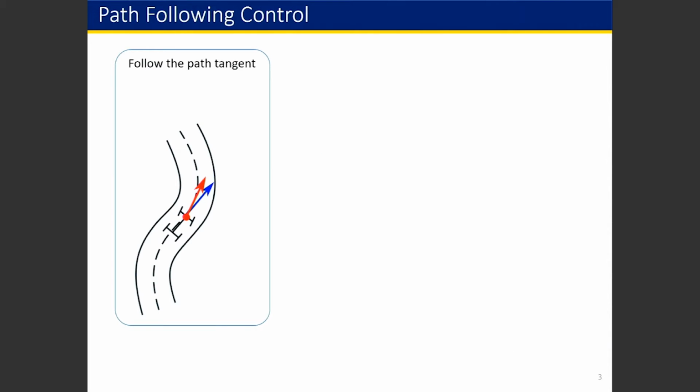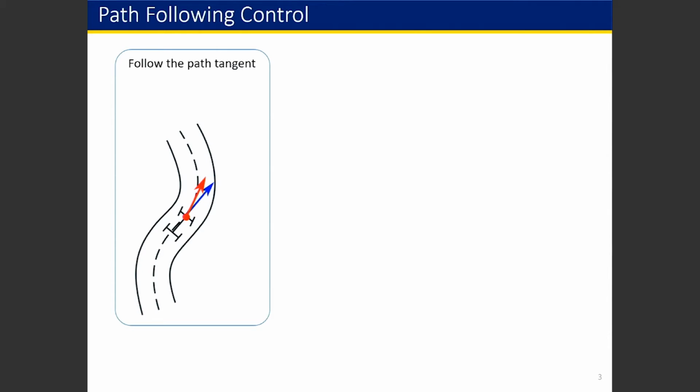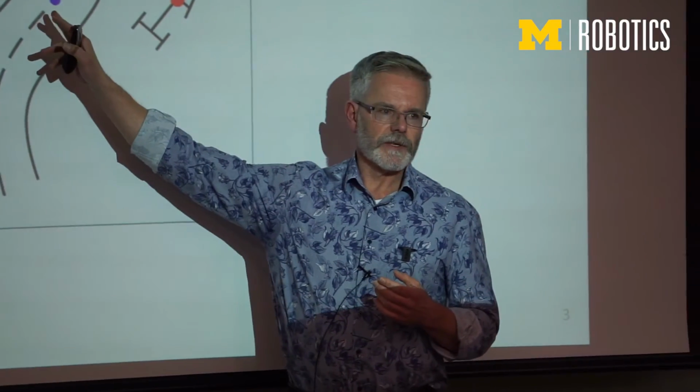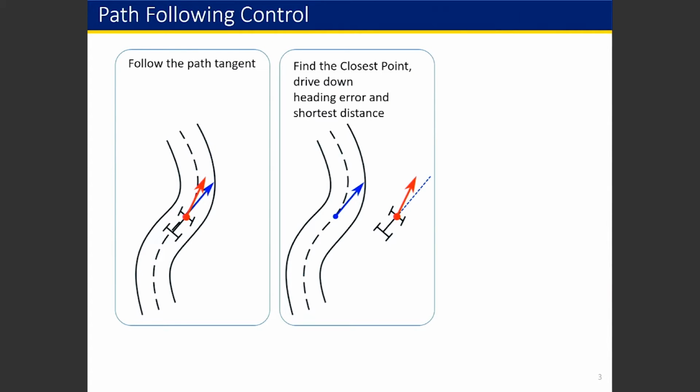It's all about following a path, simple geometry, and in 2D in the plane, we know this problem quite well. Producing path-following behavior from a vehicle, here the kinematic car, could be the bicycle model, is a relatively straightforward task. If you're on the road, in particular if you're in the middle of the road, just follow the path tangent. But if you're off the road, you've got to do something a little bit more sophisticated. There'll be a steering angle that you need to control. If all you do is follow the path tangent, say of the closest point to where you are, then what you'll do is reproduce the shape of the road, but you'll never get onto it. So we'd like to actually steer back onto the path, or what I'm going to say, stabilize the path.